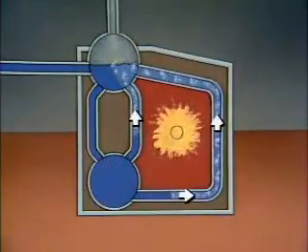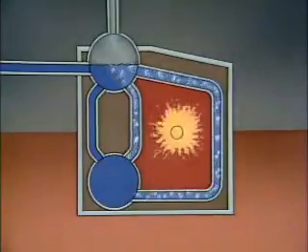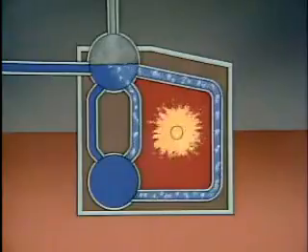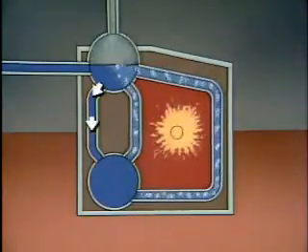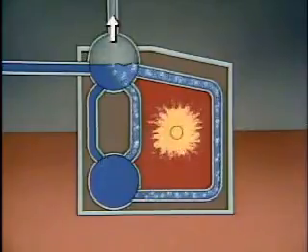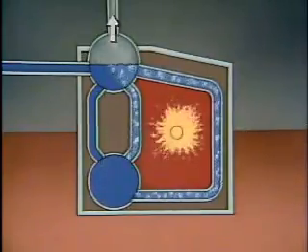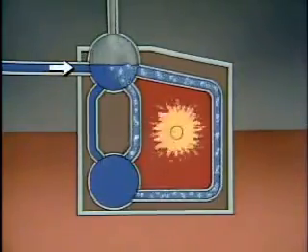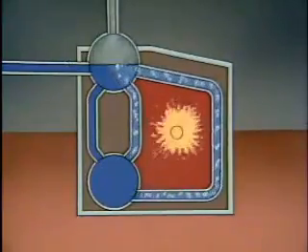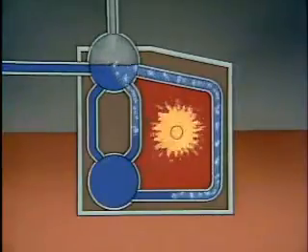Then, as the cooler water is heated, it too becomes lighter. It rises to the steam drum and is replaced by cooler, denser water. The steam flows to the plant through the steam outlet, and the water level is maintained by the water flowing through the feed water inlet. As long as combustion takes place, natural circulation continues.